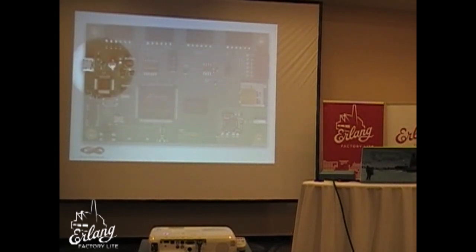There's a USB power connector, so you can charge it via your laptop or an external battery pack, something like this. And this also has a JTAG debugger via serial console, and it has serial console as well for the whole board. And there is also a specialized JTAG debugger connector in the lower left there, just above the circle here, if you want to do a hardware connection for the debugger.